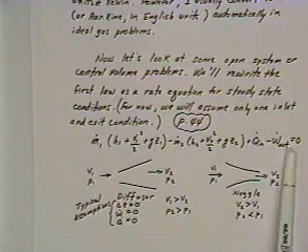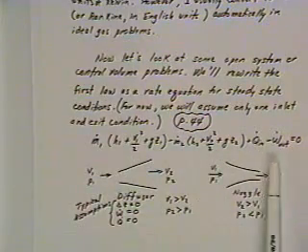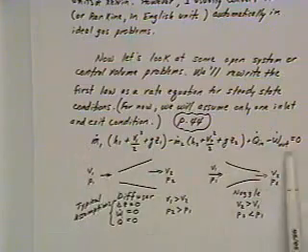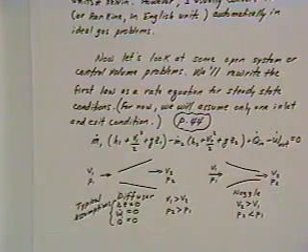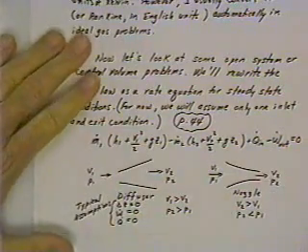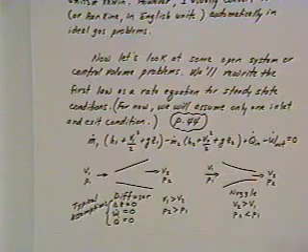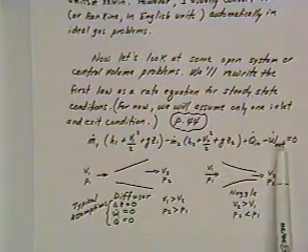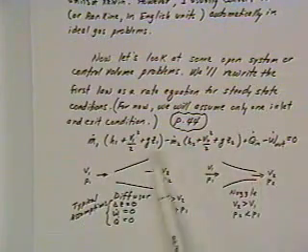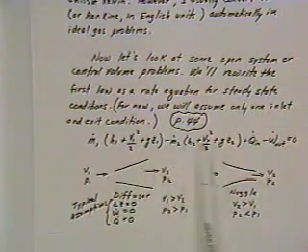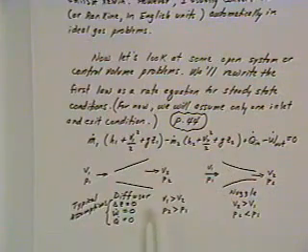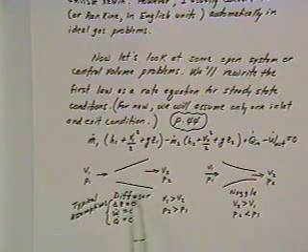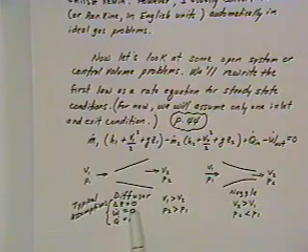And all of these things, you have to analyze each one individually and determine what terms you can throw out. If you had to solve this equation on every one, these would be more than 4-minute problems, so you really wouldn't be able to solve problems like this on this exam. In this particular case, there's no work being done for either a nozzle or a diffuser, so that term goes out, and the potential energy terms go out. Typically, you also assume that there's no heat transfer, so a typical assumption is that the change of potential energy is 0, there's no work being done, and heat transfer is equal to 0.